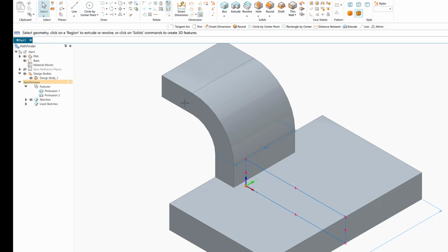Again, the sketch disappears. So I'm going to go back to the sketches, click on the sketch, right click, restore. So I restored the sketch. Okay, so I succeeded first to do this thing here. Before I move forward, let me finish the base.